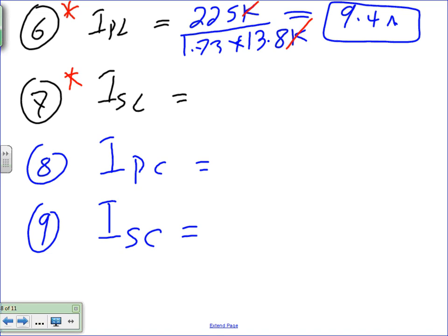94 amps? Are you kidding me? Not less than a 15 amp circuit breaker? But look at the voltage. Can you guys see what the voltage is? The voltage is huge. That's the advantage of using medium and high voltage. You can pump up the voltage and the current will go way down. By increasing the voltage, guys, we lower the current, which means you can carry smaller conductors. All these power lines will be carrying smaller conductors because the voltage is high.